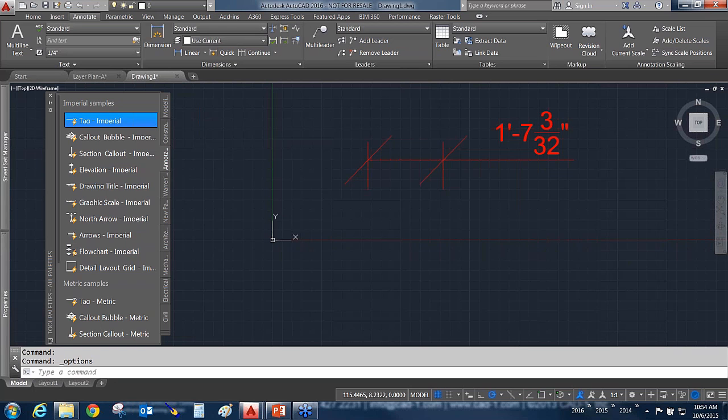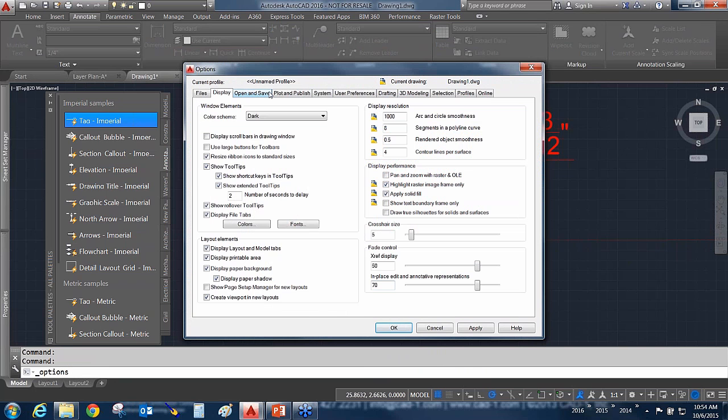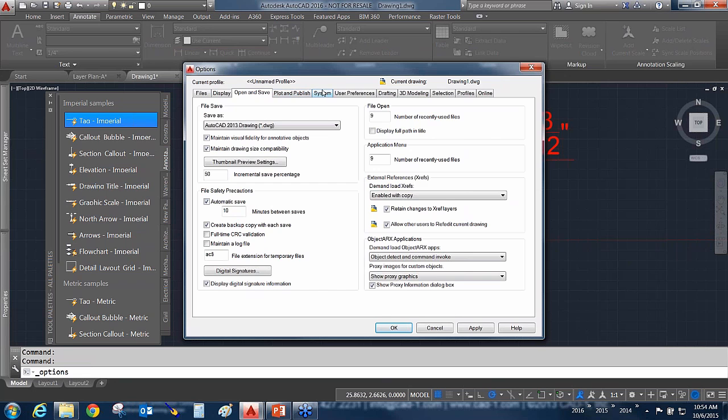Yeah, the blocks are the big ones, folks. If you're going to be using blocks inside of tool palettes, those library files can't move. They really can't move. And Mark asked, do the master files have to be in a trusted location? I think we kind of hit on that. As far as the AutoCAD trusted locations for the security services, I've got to remember where that is.